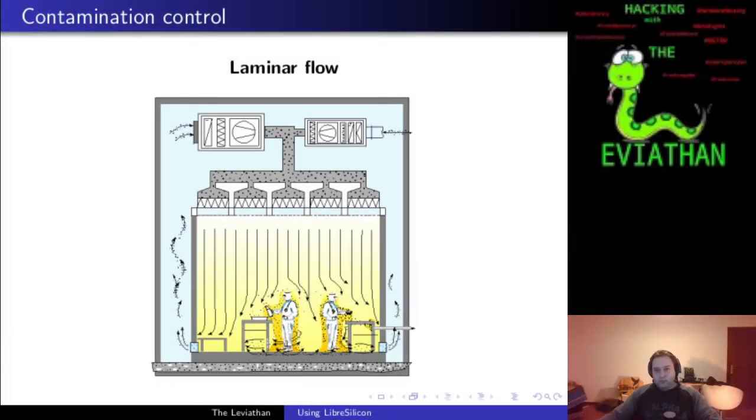In a clean room, you typically have two circulatory systems. One system pumps the air which is already in the room through multiple stages of HEPA filters, pumps it back through the ceiling, blowing all the dust towards the floor, where the air is either sucked in sideways or in some instances through perforated floorboards in the bottom of the room.